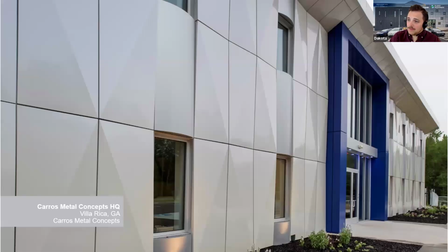Now, if we're looking for a solution that's going to be using two different types of approaches to achieve, let's say, the first flavor of metal that we talked about with the ACM exterior, right? IMPs can also still serve as that backup wall. This is a situation where we have a facade that wants to be a little bit more three-dimensional than IMPs are willing to achieve. We can still take advantage of all the benefits of IMPs and support this system as intended from that structure to make sure that it still looks the way we want it to look while having the performance of IMP in the backup, because IMPs can't necessarily achieve this type of look. It would be very hard to manufacture.